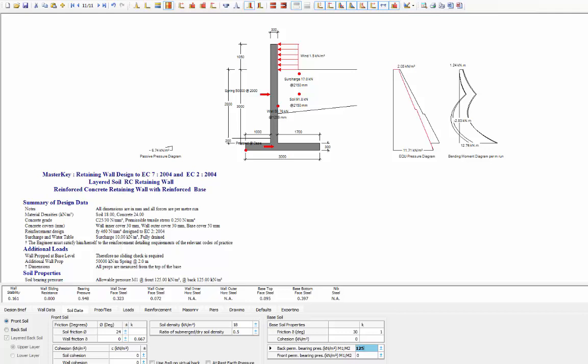I would certainly, as a structural engineer, just be asking a geotechnical guy what my bearing pressures are for M1 and M2 conditions. If you want to specify two conditions, you can just go M2 and a semicolon and put in the second capacity. So under the second capacity for M2 loading, your bearing pressure is 150. If you want the front and back to have different values, you can again put in a front. If not, 0 means they're the same.